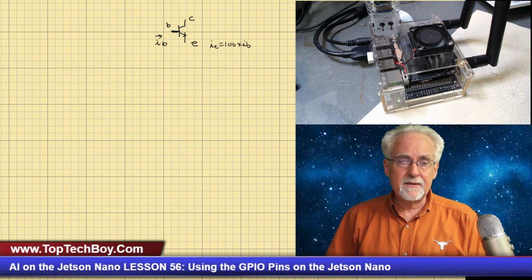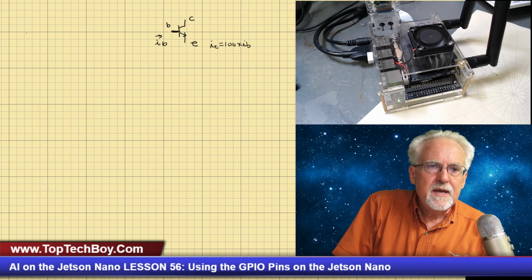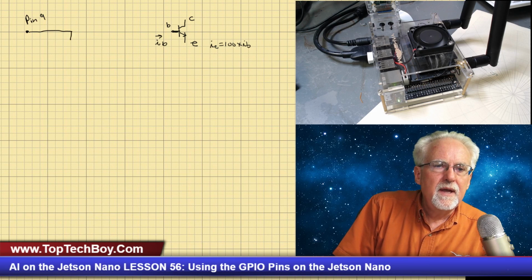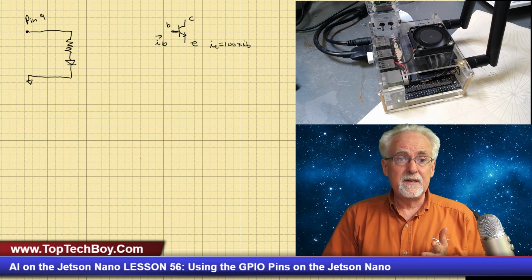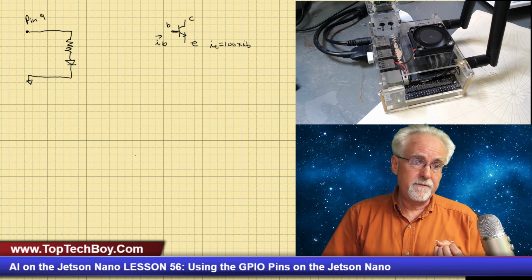So how will we make this LED work? Well, let's go back and think of the old Arduino days. In the old Arduino days, let's say that we have pin 9, and you would come from pin 9 over, go through a current limiting resistor, and then go to the diode, and then come back and ground things at the Arduino ground. Now, if you turn pin 9 on, the LED comes on. If you turn pin 9 off, the LED goes off.